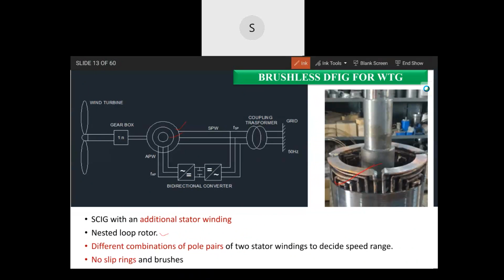Only issue is that it cannot be just an ordinary squirrel cage. In an ordinary squirrel cage, the induction is coming from one winding only. So here there is a mix actually. The two windings of the stator will be having different poles also. So that's why a special design is required, so it can rotate. Induction will be handled with that rotor circuit. Okay, sir.